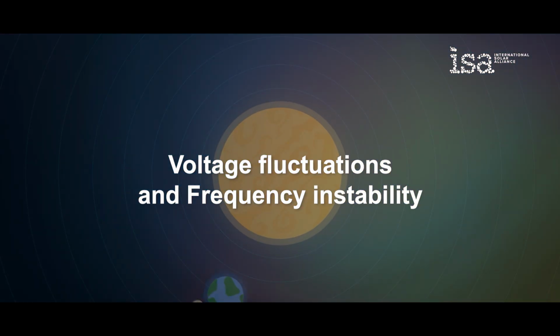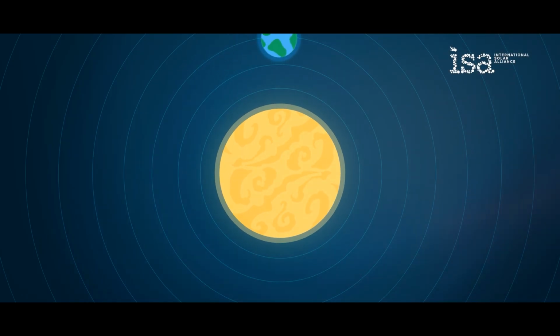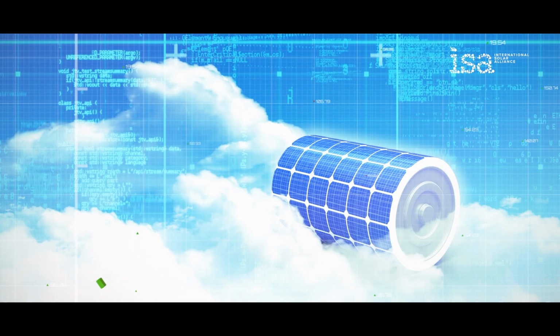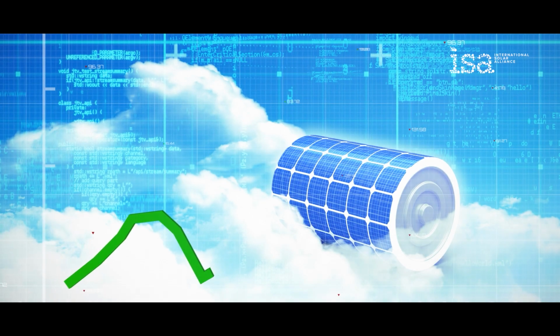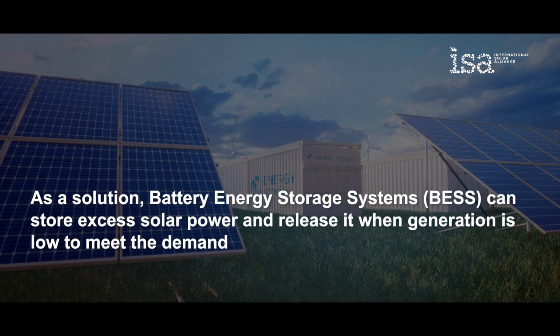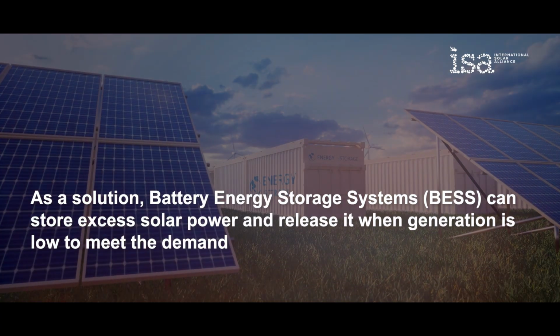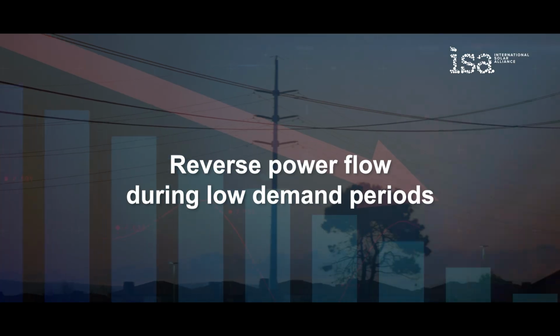Voltage fluctuations and frequency instability. Solar power generation fluctuates depending on weather and time of day. This variability must be managed to maintain a stable balance between supply and demand. As a solution, battery energy storage systems (BESS) can store excess solar power and release it when generation is low to meet the demand. Reverse power flow during low demand periods.